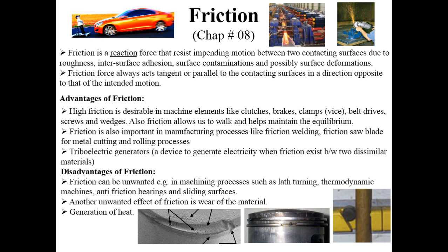The word impending here means that the motion is about to take place, because remember we are dealing with statics. Impending motion means that the body will be on the verge of having motion. It is not in motion, but it is on the verge of having motion. So that motion will be restricted by the friction force, which is a reaction force.